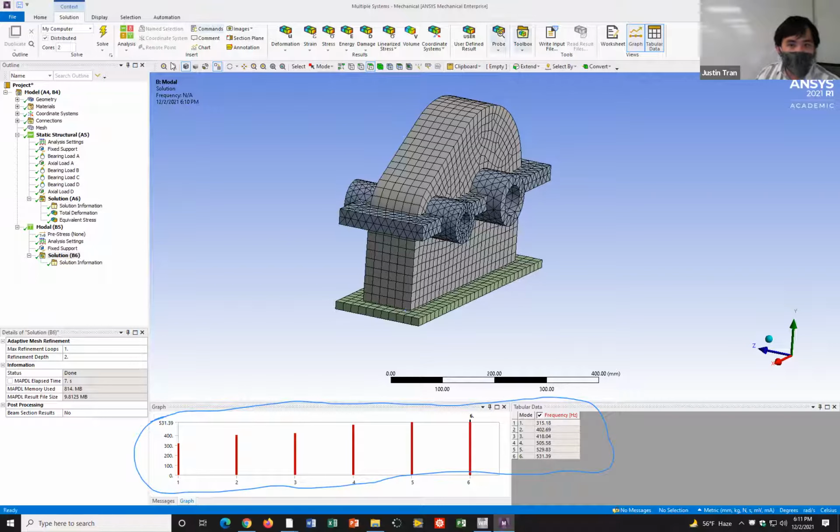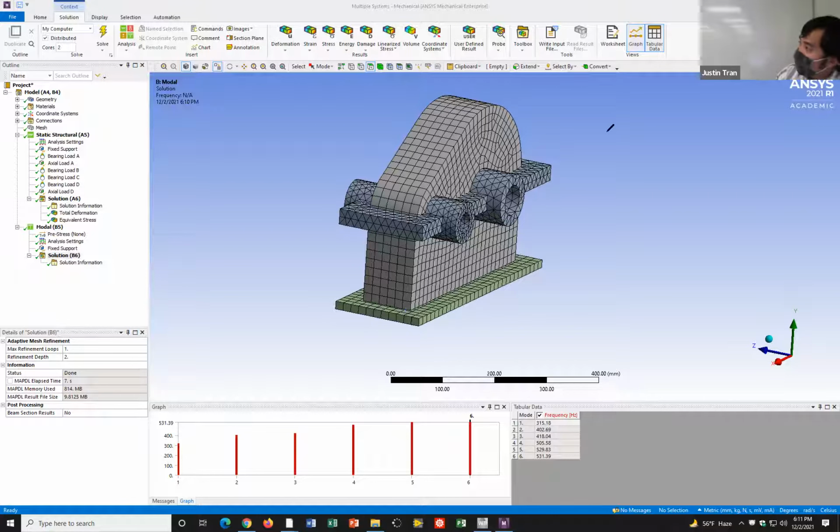Another thing we would like to see is the mode shapes. If you remember from the lecture on Tuesday, we have resonance in our string, and the resonance could take any number of shapes. We might have a mode that looks like this, or like this, or one that looks like this too. Depending on what frequency we're loading the string at, we might view different resonance modes, in other words, different resonance shapes. We can view what those resonance shapes look like for a 3D application like this too.